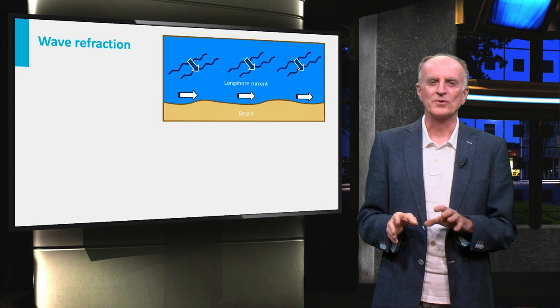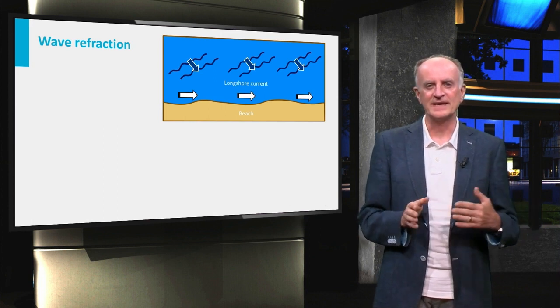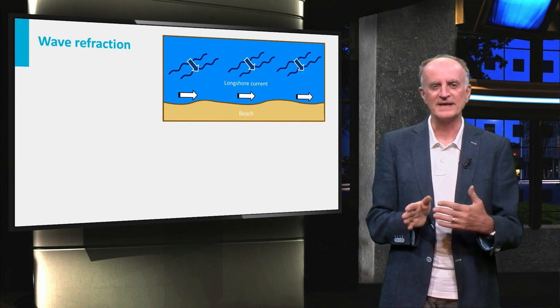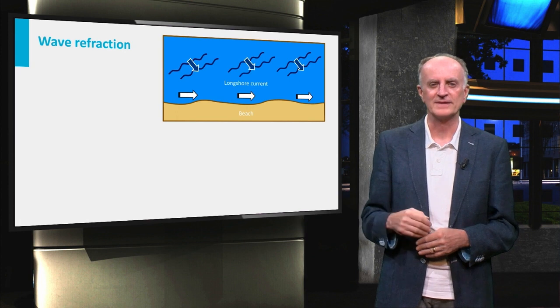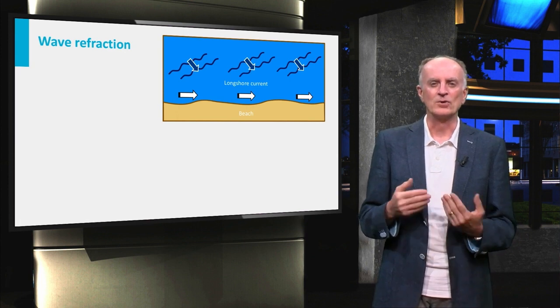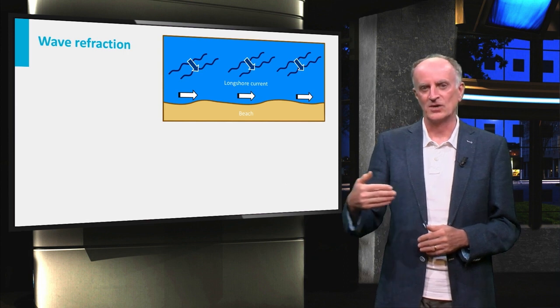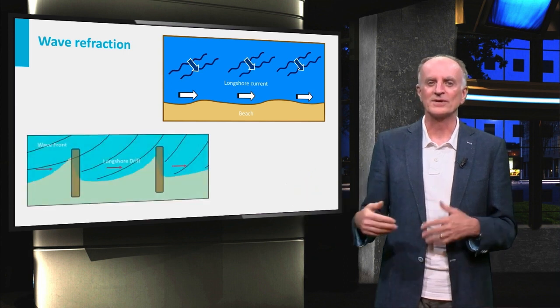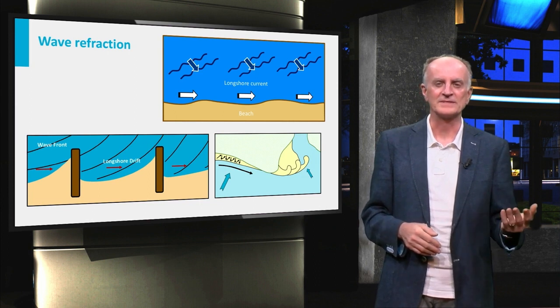Winds and waves do not always move perpendicular to the coast and are often oblique to it. In this case, waves hitting the coast are deflected, giving rise to a component of movement parallel to the coast itself. These are called along-shore currents, which can erode, transport, or deposit sand along the coast. Walking along the coast, you see typical effects of along-shore currents, such as coastal groins and spits.